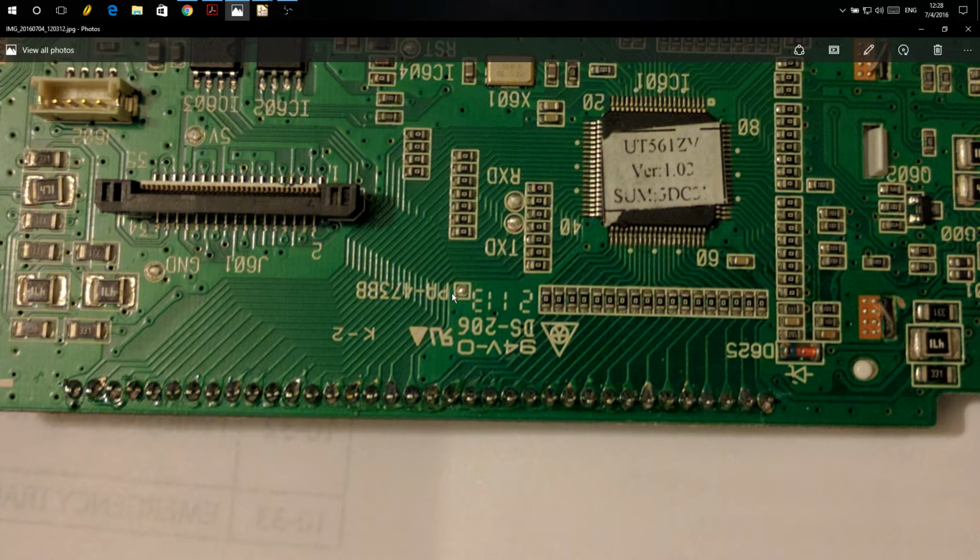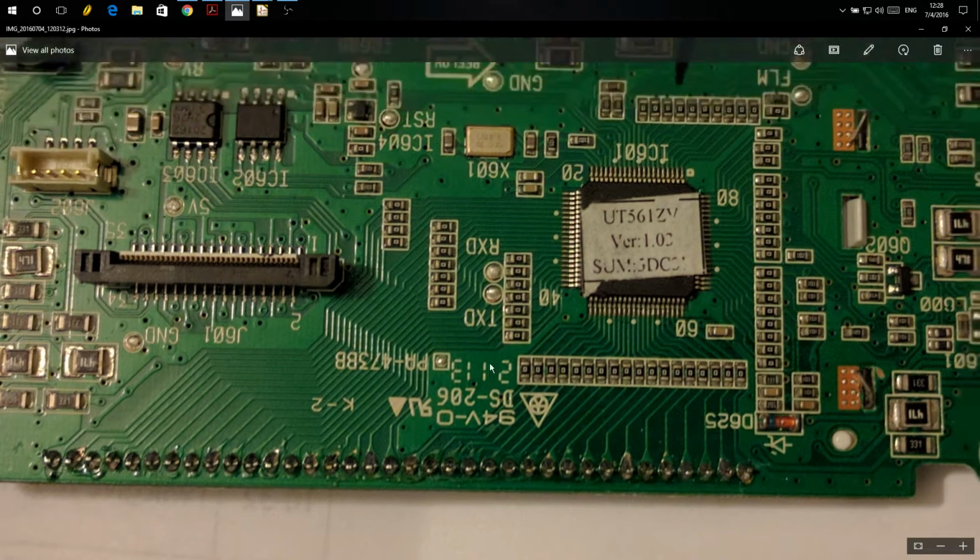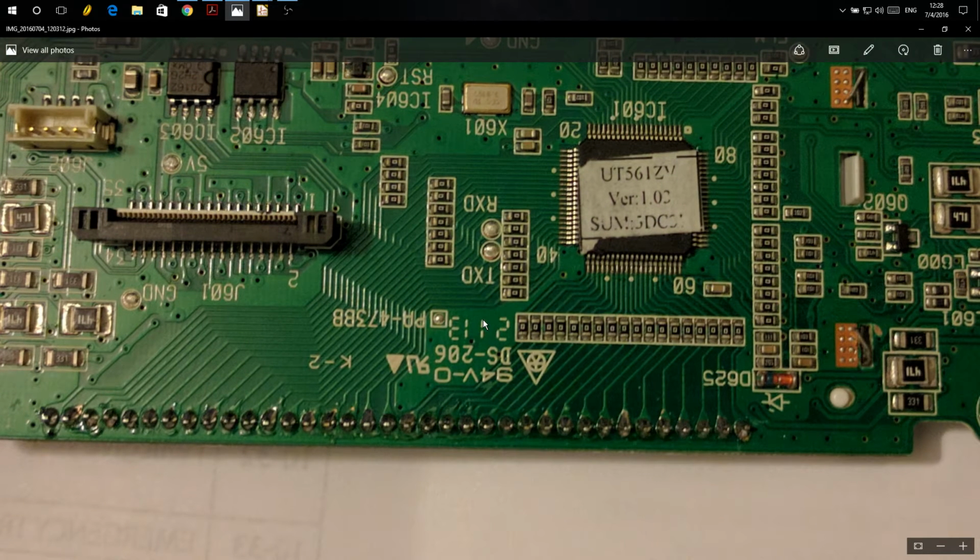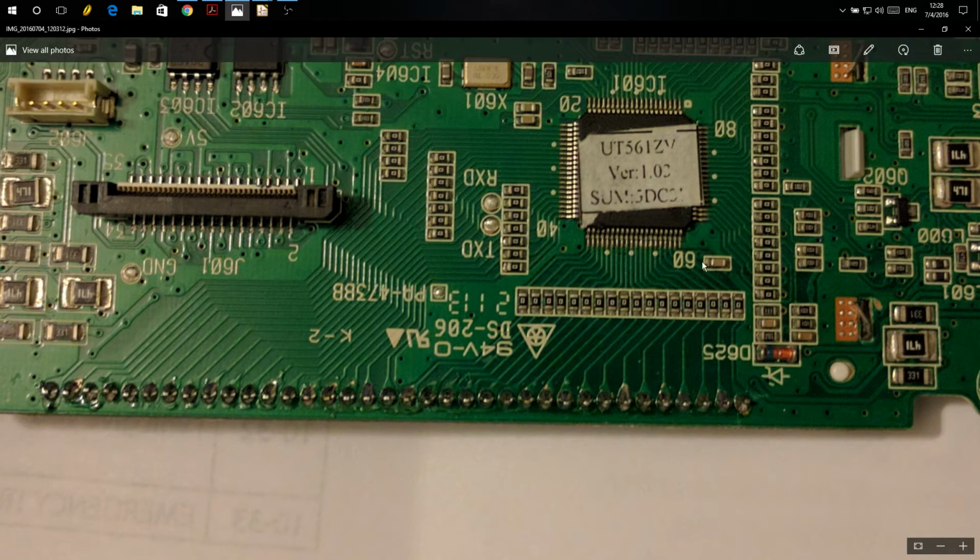And basically, if you encounter one of these displays, you pretty much know right off the bat whether it's passive or active, because a passive display is going to have obviously a lot of connections. This many connections, 36, is not reasonable for an active display, because it's going to be a data bus. It's usually a parallel or serial bus that's going to go into it. Maybe you'll have some other things, but you certainly wouldn't have this many connections. Another thing of note is that the display pattern is fixed, so that also generally indicates it's a passive display.